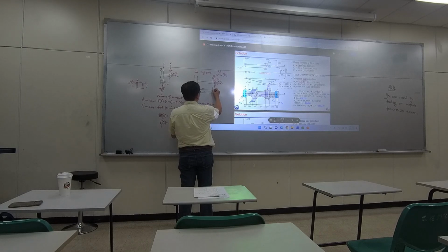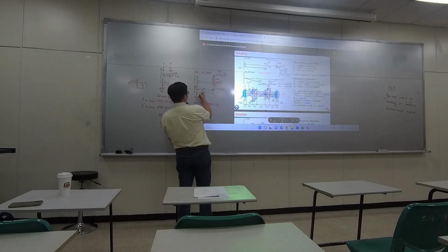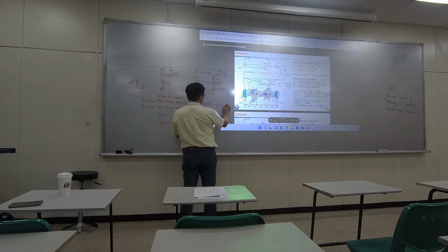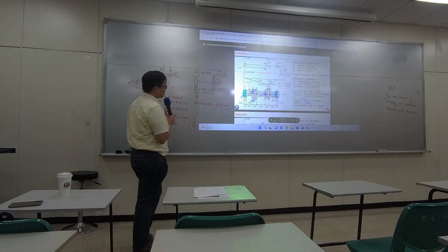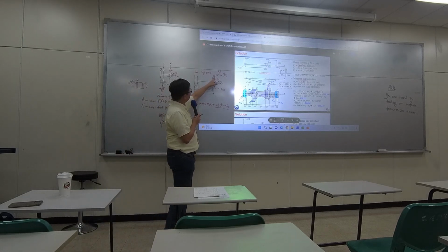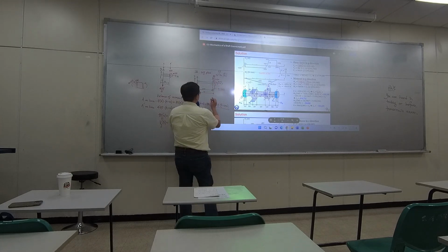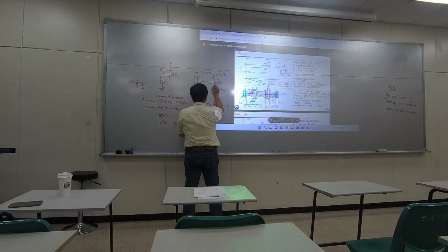So what's the width right here? It's gonna be x minus 240. Here's 240, here's x. So x minus 240. So this is how much equivalent single load this portion has. So you convert it into a single load. But the exact position is right at the middle.